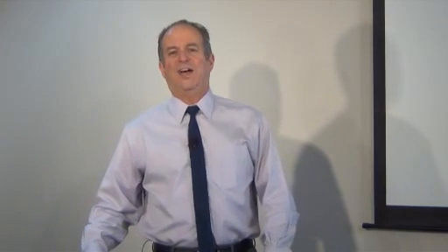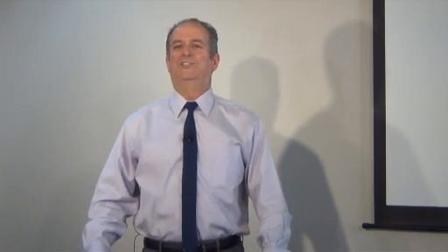You have charts like this. Notice that when the number gets bigger, going from 10 to 12 to 15, the size is actually getting smaller. The diameter gets smaller and the resistance gets bigger. So as the number gets larger, the wire gets smaller and the resistance gets greater, just like we were talking about.